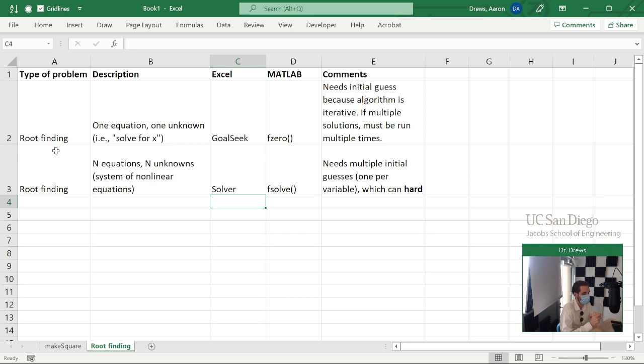We're going to leave these till later and focus just on the first one, primarily because when we want to make those guesses, we usually have a physical reason behind those guesses. Like we do it all the time in 113, and the things that we're guessing are things like reactor temperature and composition and pressure. And we can ballpark what those ought to be based on, for example, the inlet, right? The temperature, if the inlet's 500 K, it's probably going to be somewhere around 500 K coming out. It's not going to be a million K coming out. So a lot of those guesses are dictated by the problem itself, which is a little harder to do in the abstract because you don't know what those problems are.